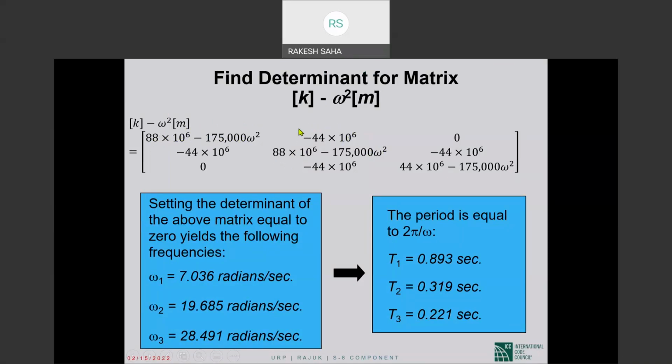It is just the stiffness. Anyway, if you go back to our stiffness matrix and our mass matrix, you will see that we have written here the k minus omega squared m term. Okay. I don't want to go back and forth. It takes time and may even be confusing, but that's precisely what we have done. We have our k matrix, we have our m matrix. We are assembling the k minus omega squared m matrix.